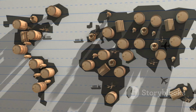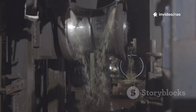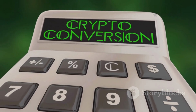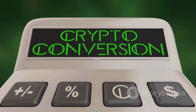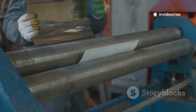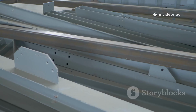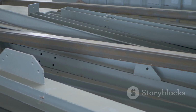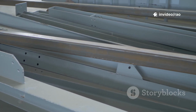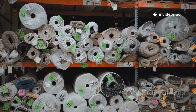For larger projects and commercial transactions, steel quantities are often discussed in quintals. A quintal is a unit of mass equal to 100 kilograms. Total weight in quintals equals total weight in kilograms divided by 100. Total weight in quintals equals 159.81 divided by 100 equals 1.5981 quintals. For practical purposes, this can be rounded to 1.60 quintals. Thus, for our 4 meter by 3 meter slab, we require approximately 160 kilograms of 12 millimeter steel. This final figure is what would be used for procurement and cost estimation.